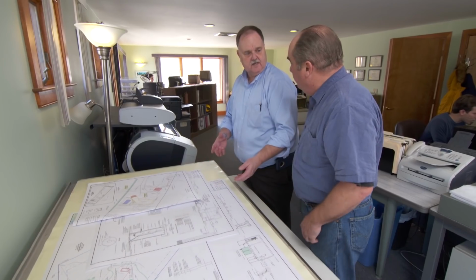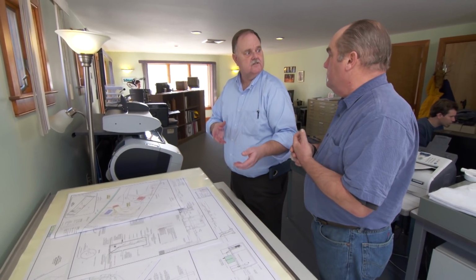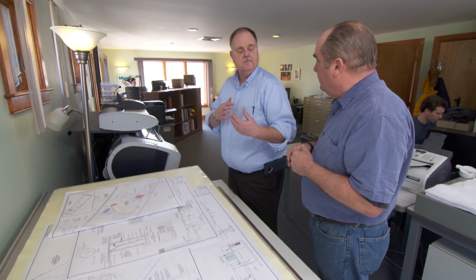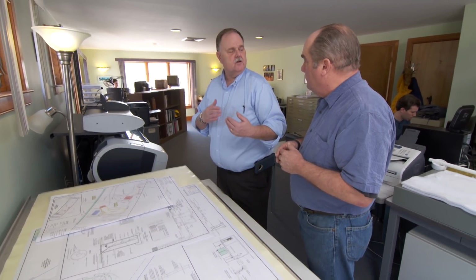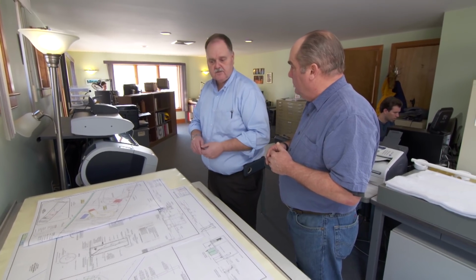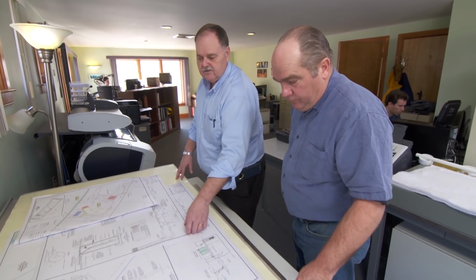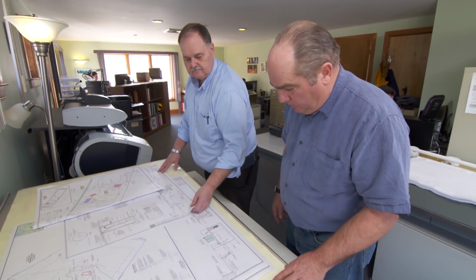We can't use it on this site because the Adams property is in a critical resource area. Okay, what does that mean? That means it's in an environmentally sensitive area, and because of the coastal ponds, the salt ponds along the south shore, we have to use a denitrification system. Because that's the big issue, nitrogen? Nitrogen. Okay. So we have to reduce the nitrogen going into the groundwater. So how do we get around that?